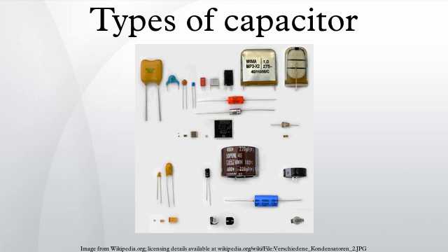Variable capacitors include capacitors that use a mechanical construction to change the distance between the plates, or the amount of plate surface area which overlaps. They mostly use air as dielectric medium. Semiconductor variable capacitance diodes are not capacitors in the sense of passive components but can change their capacitance as a function of the applied reverse bias voltage and are used like a variable capacitor. They have replaced much of the tuning in trimmer capacitors.